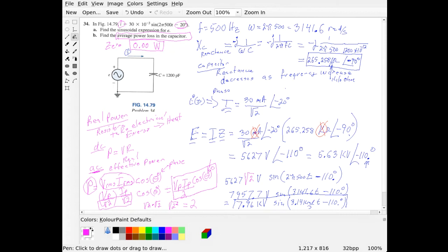Now, capacitors are pretty much ideal. They don't get hot normally. If you have a capacitor getting hot, that means it's actually leaking current. The current is somehow sneaking through that dielectric, and it's not supposed to, which means your capacitor is bad. So capacitors really don't heat up.